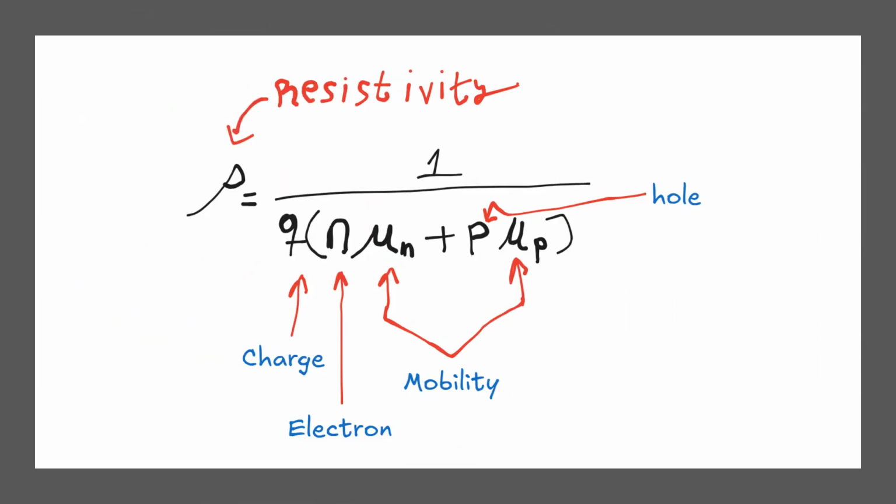And we would use a 4-point probe because we want to find the resistivity of this material. What does the resistivity hold for us? Well, it holds some unknowns that we care about for the material. So the concentration of electrons, its respective mobility, as well as the concentration of holes and its respective mobility. So if we have the resistivity, that's one less thing we need to find, and we could try to find the concentration and the mobility of this material.